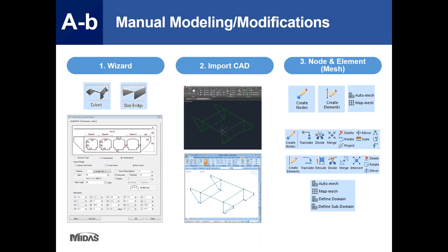And once you import it, that's just a bunch of lines and elements and nodes. And from that point on, if you need to create a 3D model, if you actually need to mesh it or manually create plate elements one by one, whatever the case may be, you can handle that using the node and element functions in our program. And I'll be showing this number 2, importing the CAD approach, and also how you could utilize the node and element functions to mesh your imported CAD drawing.